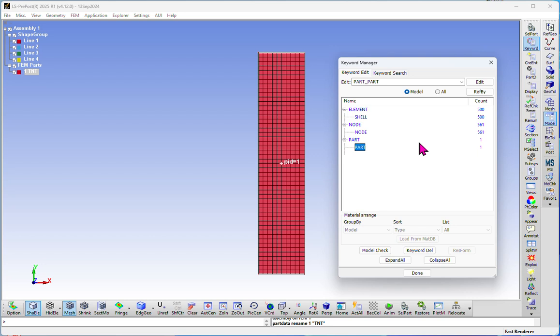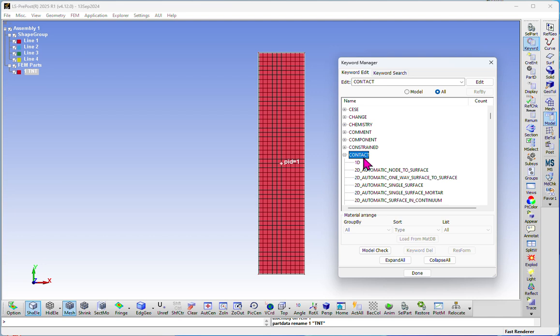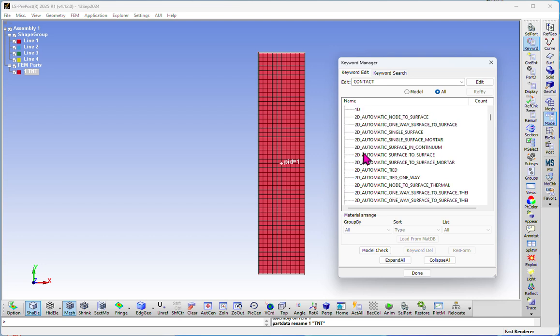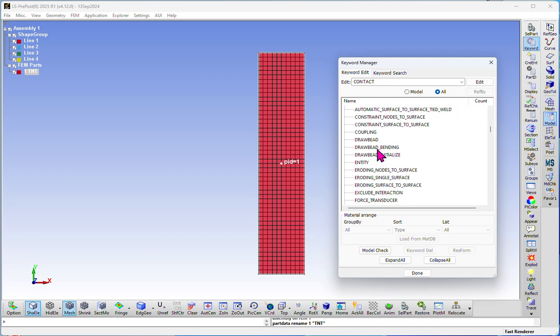The first thing I'm going to do is click on the All button so I can get to the other model options. And I'm going to add in a control for the termination. So I need to end the run of this model at some point in time. For this model, we're going to run in units of centimeters and microseconds and megabar. So I'm going to enter all the units like that. And that is a traditional unit system when you're doing HE shock.